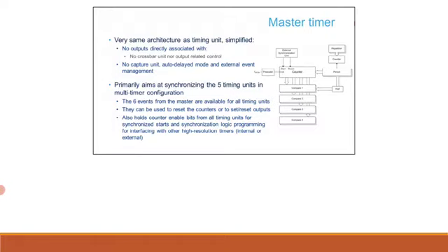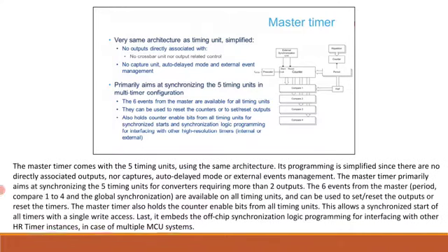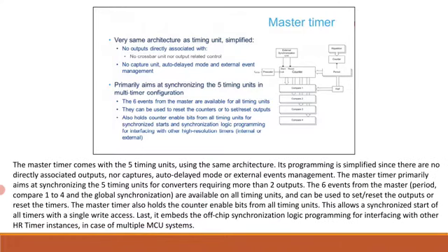or reset the timers. The master timer also holds the counter enable bits from all timing units. This allows a synchronized start of all timers with a single write access. Last, it embeds the off-chip synchronization logic programming for interfacing with other HR timer instances in case of multiple MCU systems. Have a look at this. Then we will move on to the external events.